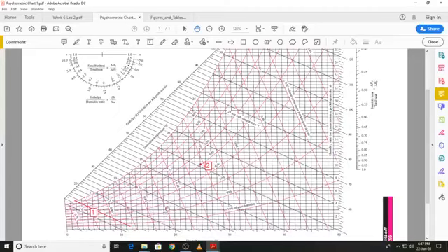We will have to use the energy balance, which will require the enthalpies. So if I just look at state 1, I can find out the specific enthalpy and the specific volume at state 1. And if I look at a constant enthalpy line which passes through state 1,